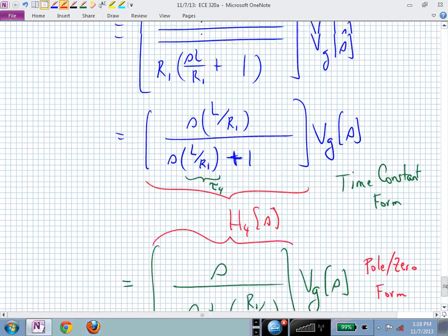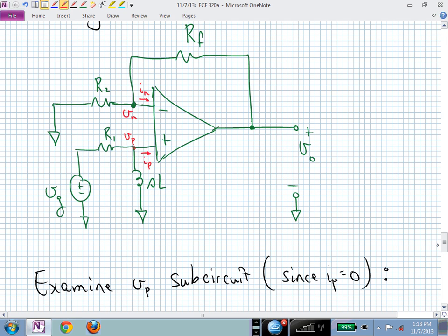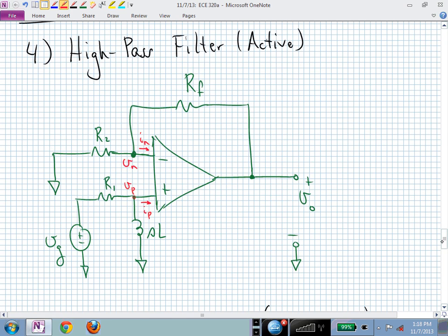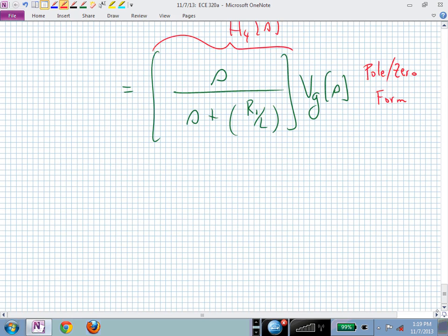And we could actually, where were we? We've just analyzed this subcircuit, haven't we? Down below. But what do we know if we disconnected all of that? If we just connected V sub P to ground and forgot this circuit, what do we have remaining? Do you recognize that circuit? An inverting amplifier. So now whatever is appearing at V sub P is essentially going to go through an inverting amplifier. So we've introduced a little bit of a scale change or a gain change on top of this filter behavior that we derived in the lower left-hand picture. So we're not quite done, but we could even just analyze this in terms of its frequency behavior.